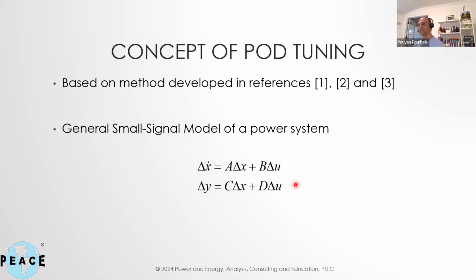It's always a set of differential equations plus a set of algebraic equations that set the boundary conditions. And the only difference when we go from, say, an EMT model to a positive sequence model is, for example, in EMT, even the lines and the capacitors and everything are still differential equations.